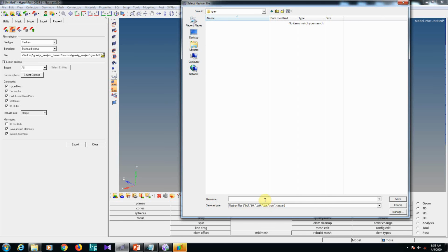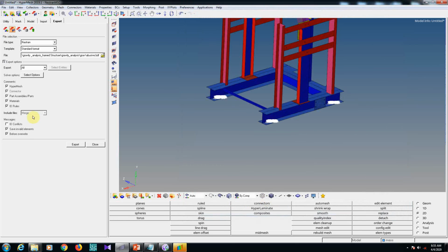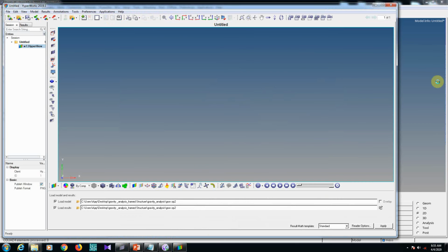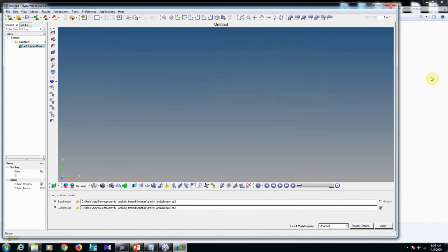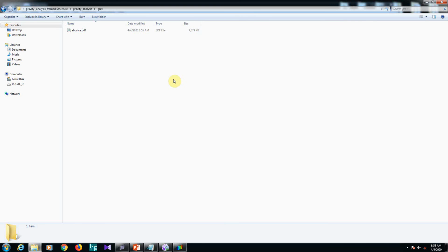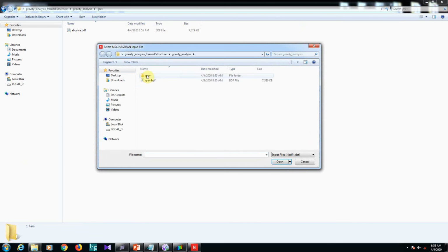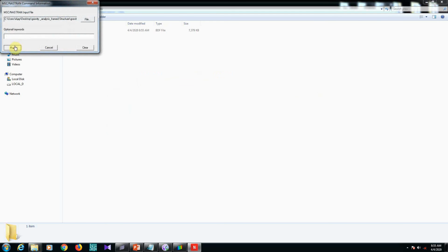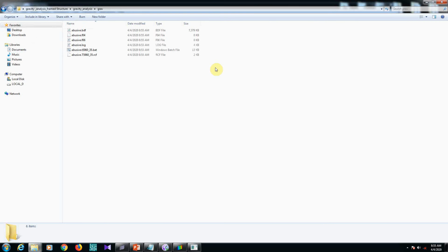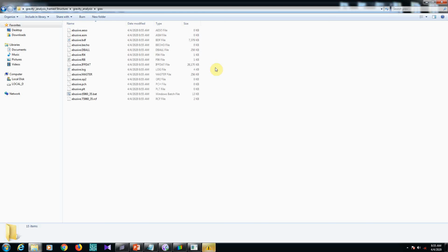Abusive load. So in worst case, under road load condition, what will be the effect on the structure, for example a vehicle running on a rough road or a smooth road. If the road has humps, for example a vehicle moving with a velocity of 50 km/h, and suddenly a hump is in front of your vehicle at that time, what is the acceleration the structure will experience, means what is the force it will experience.